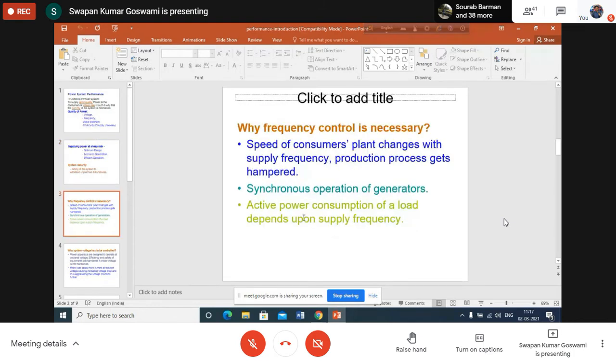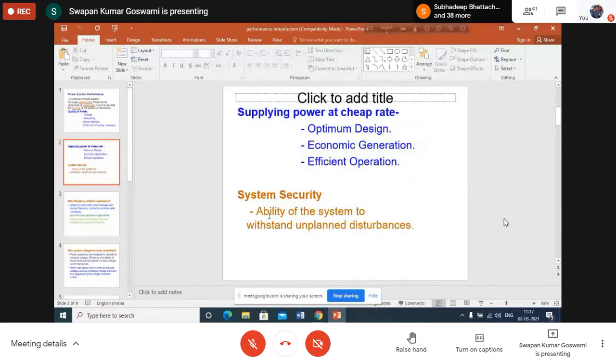And another thing is regarding the integrated operation of the power system. We have mentioned the collapse of the total system. Collapse of the total system is associated with the so-called stability of the power system, so we shall be discussing the stability of the power system also. What is stability? In the conventional meaning, stability of a power system means the ability of the system to maintain normal operation after a large disturbance. Stability in the past was meant in this way, that means the stability of synchronous machines.